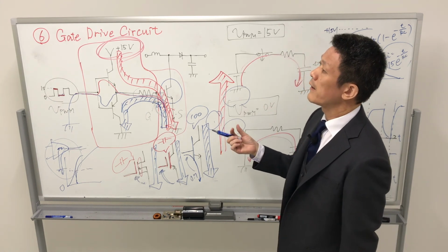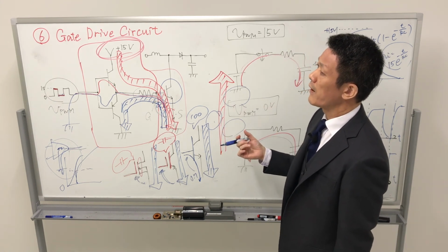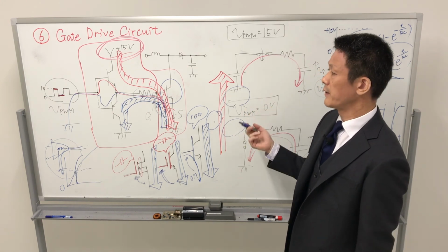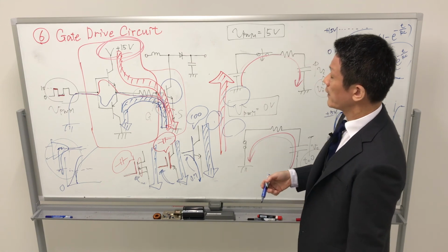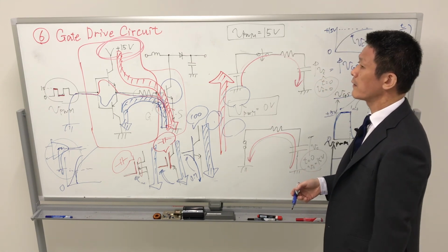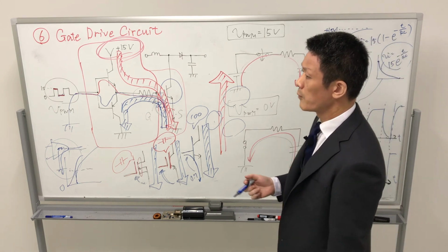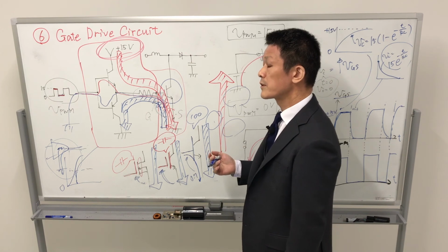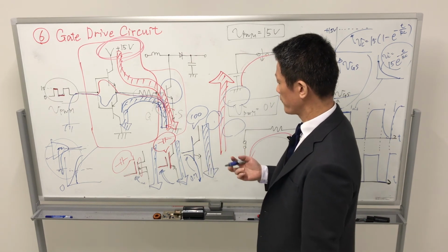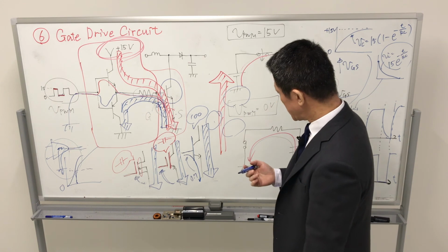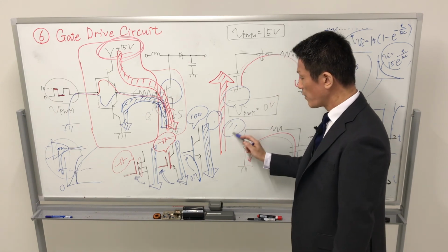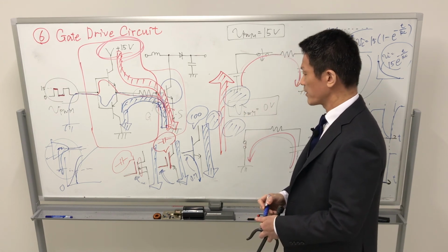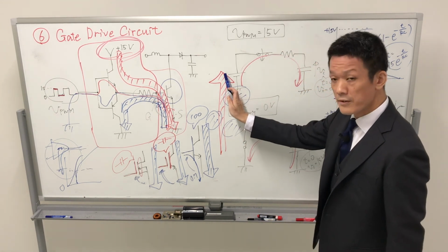Capacitor type isolation is usually applied by Texas Instruments, and many Japanese companies, for silicon carbide MOSFET driving. Transformer isolation is a good match, but that is know-how and additional discussion. But the essence is important.